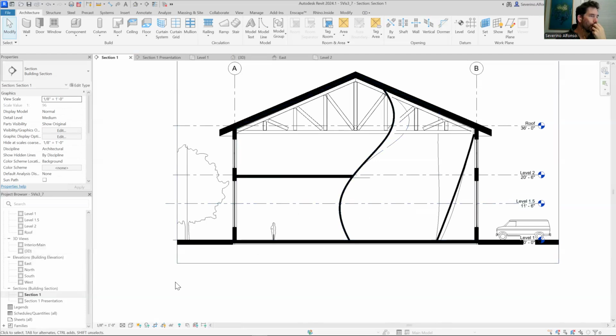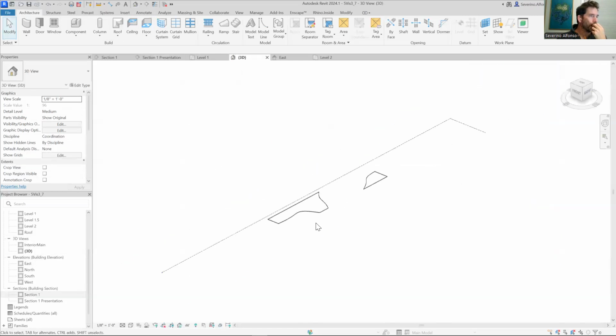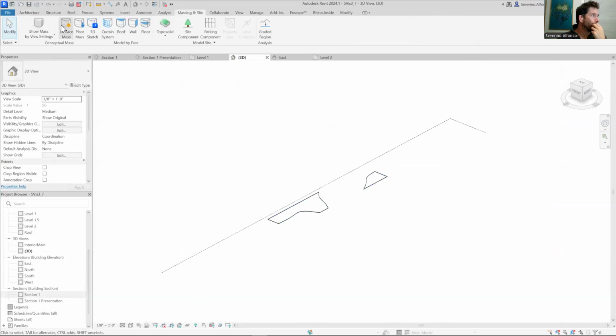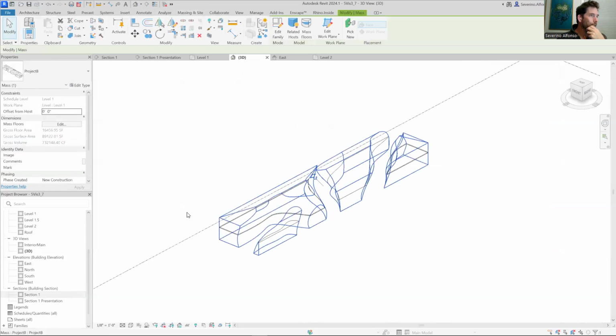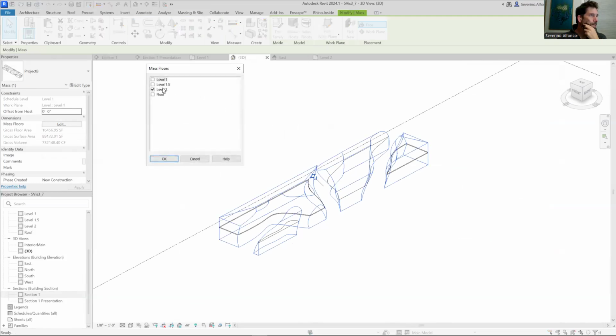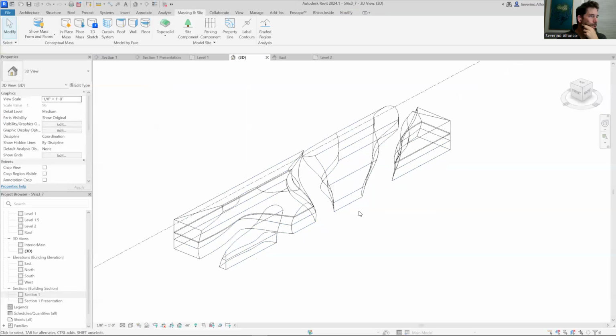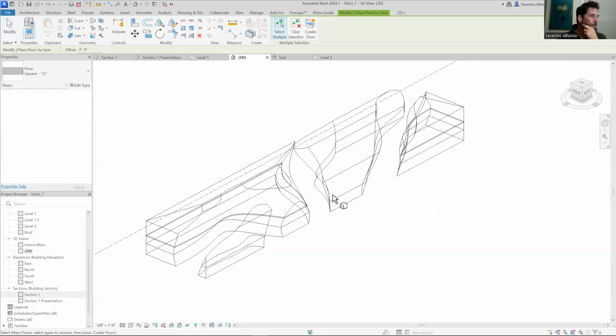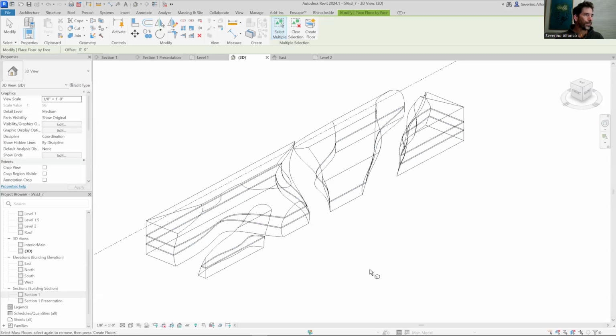So, for example, I'm going to create another small floor here for us to figure out. So what I'm going to do is go again to the 3D. I'm going to turn on under massing inside the mass, select this element and create, for example, another glass floor here. It's going to be on level 1.5. I create that section, and under floors, I'm going to select this element with the same type of floor, wood joist, and create floor. Okay.